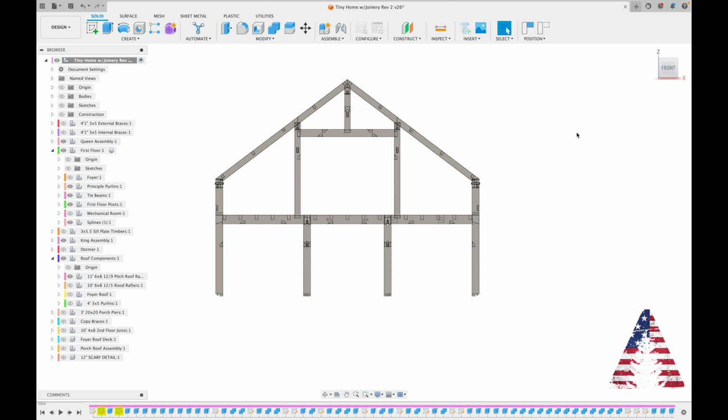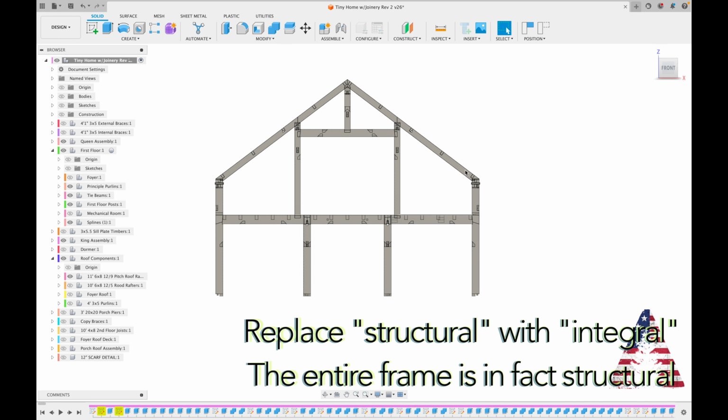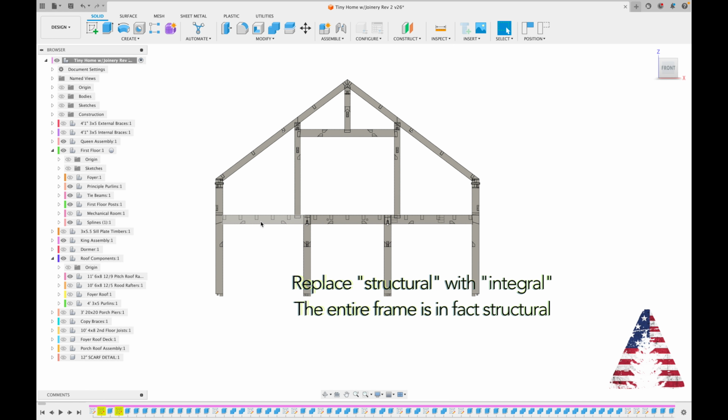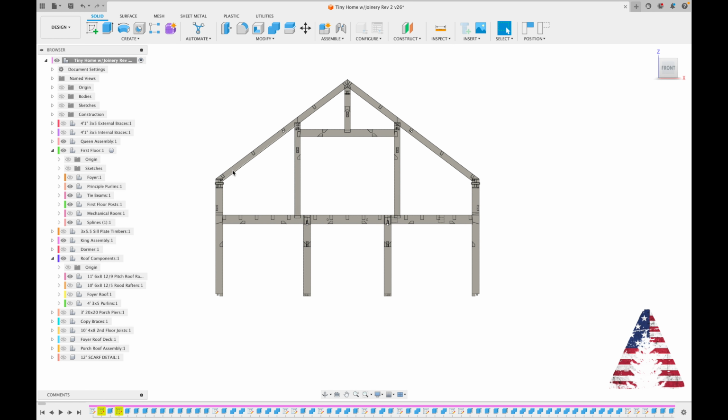I think in a lot of modern timber frames you see this. They look nice. They go up pretty easy. They're fantastic structures. The issue here is these are all structural components in that case. So the rafters are structural. So this would be a principal rafter. The collar tie, these would be structural and all have to tie together. And this tie beam here then becomes very important and structural, and I'll go through that in just a second. And there's a few challenges with this design.